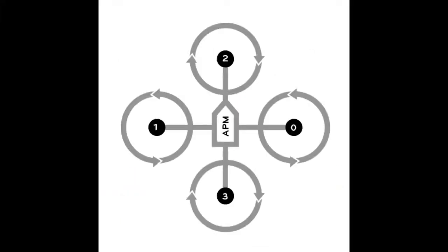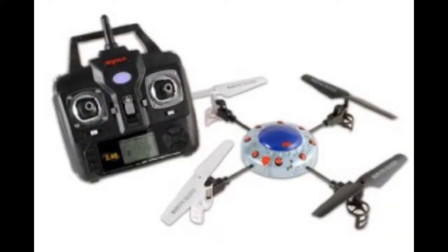It is through the RPM of each individual propeller that a quadcopter has the ability to go in any direction it wants to. If you want to lift a quadcopter in the positive Z direction, you will have to increase the RPM of all four motors simultaneously, vice versa if you want to descend. If you want to move forward in the Y direction, you will have to decrease the RPM of the two front propellers and increase the RPM of the two back propellers. To have this work properly, a quadcopter needs an MC multi-rotor control system. This makes 600 or more adjustments per second. Like I said before, this is tremendously hard for a human to do.